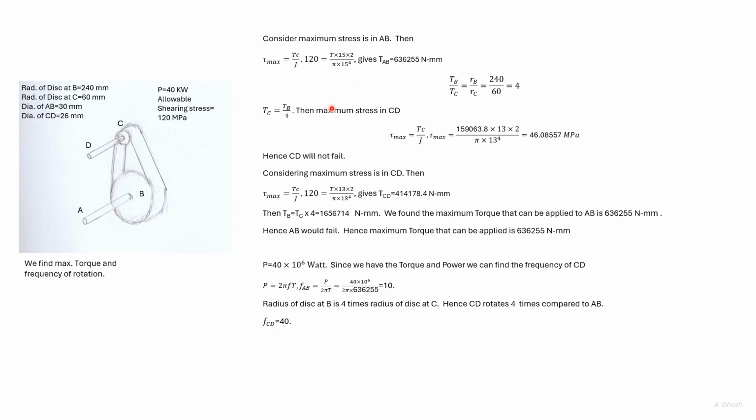This means the ratio of the angle of rotation of disk B to disk C will be the inverse of the radii. Hence, both relationships of torque and angle of twist are the same as those of two adjacent gears in this case.